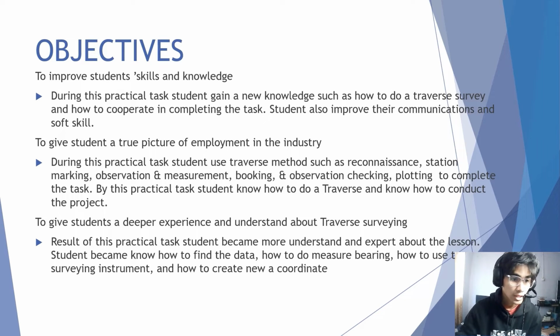Next, to give students a true picture of employment in the industry. During this practical task, students use traverse methods such as recognition, station marking, observation and measurement, booking and observation, checking, and plotting to complete the task. By this practical task, students know how to do a traverse and how to conduct the project.